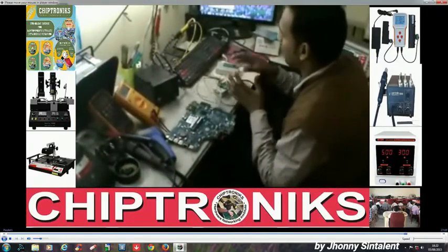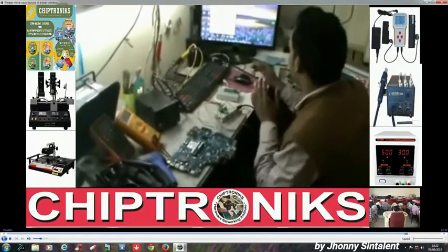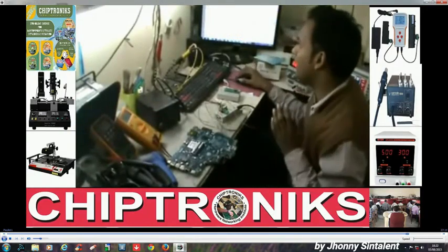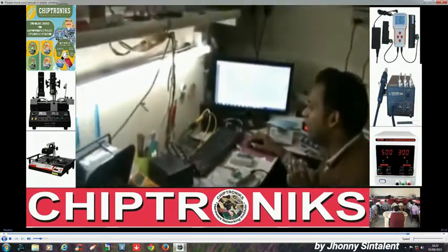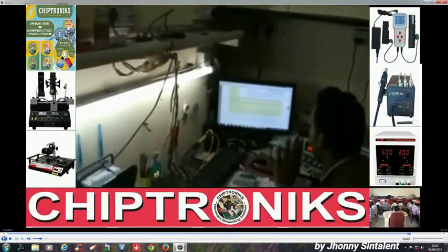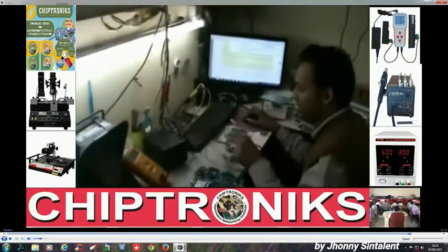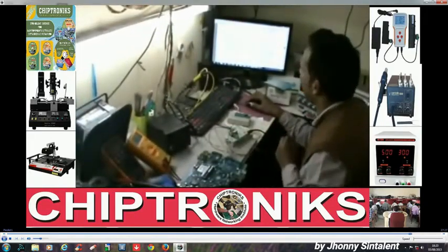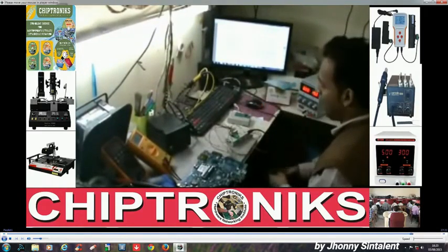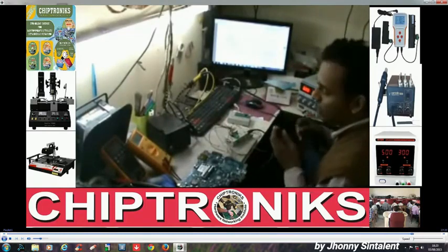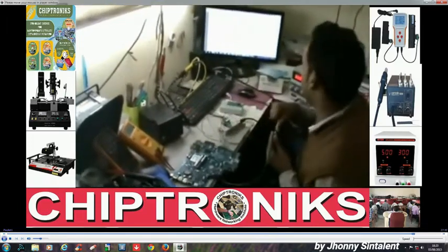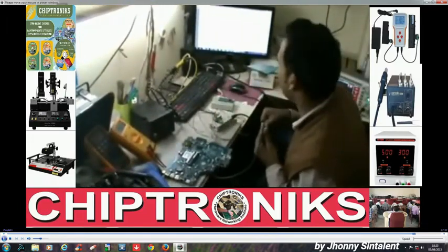But before using this RT809F, we have to configure our board, and configuring our board requires these 4 pins and this 1 pin. That is 5 connections from here to the board. 4 for reading this embedded flash and 1 for entering this IO controller into test mode. And you see I'm supplying the power with the DC supply to the board. I have not pressed the power button yet.